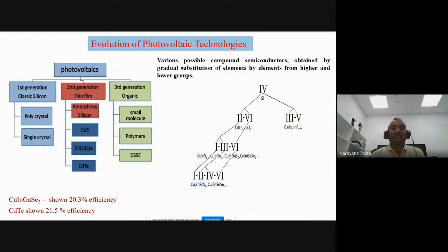So one concept we have to remember for solar cells is the absorption coefficient. The absorption coefficient is inversely proportional to the thickness of the material. Generally, silicon is an indirect band gap semiconductor, so it absorbs less solar radiation. We need very thick material to absorb the incident solar spectrum. That's why this is called a wafer-based solar cell. It is about 200 micrometers, thick material. These are polycrystalline materials. These are very well-studied, well-established materials. Currently, 80% of the market is dominated by silicon solar cells.